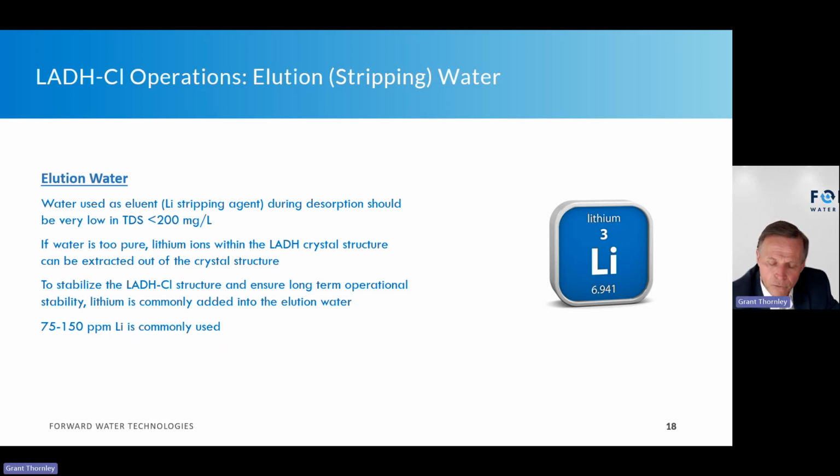However, what I found through multiple tests and evaluations is that if you only use water, I mean a high purity, low TDS water, what I find is that you start stripping lithium out of the physical lithium aluminum hydroxide layer. Remember, lithium is chemically part of the layered structure, right?